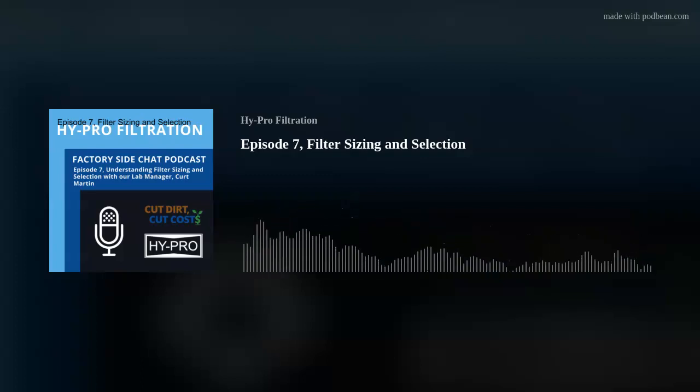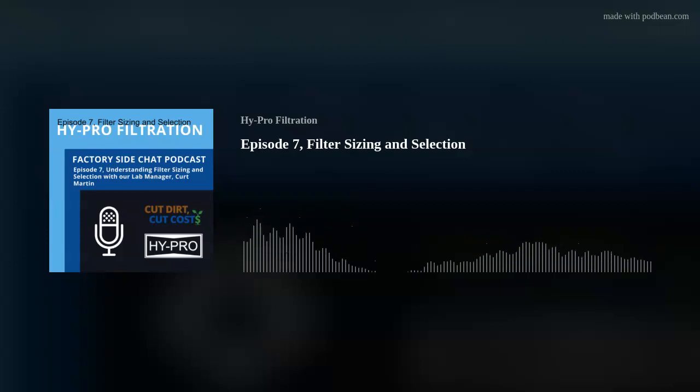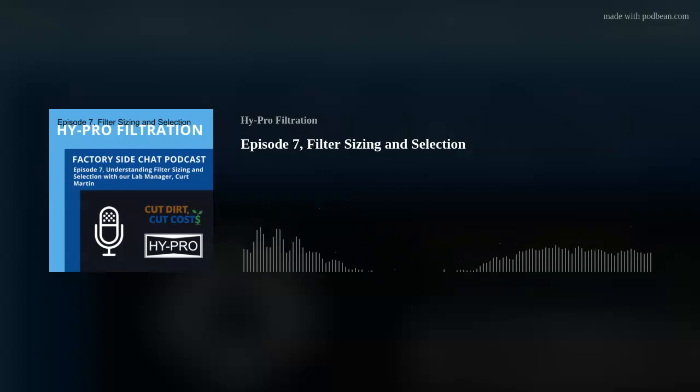Typically about a third of the way through the element's life, that's when you really start to see the differential pressure increase. For example, if you get an element with a terminal DP of 60 PSID, around 20 PSID is when you start to see that DP curve ramp up really rapidly.